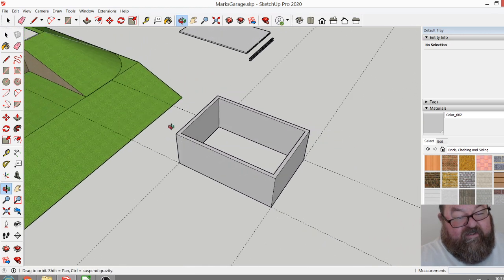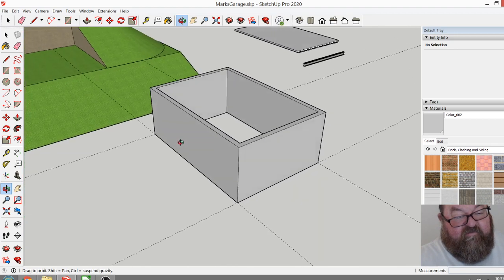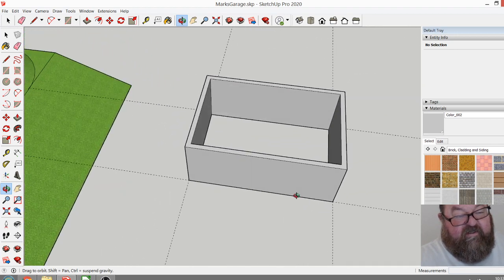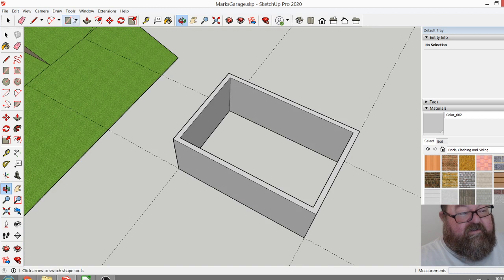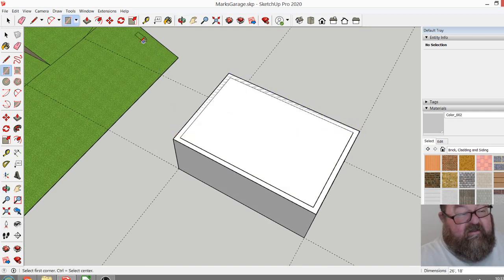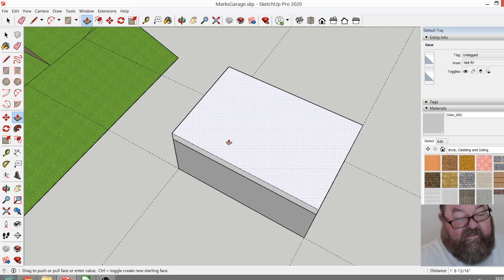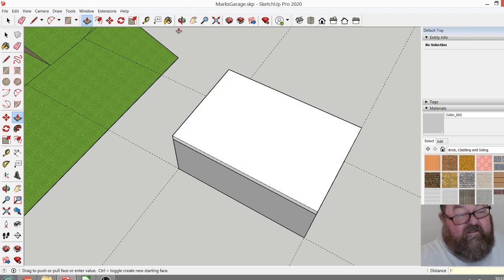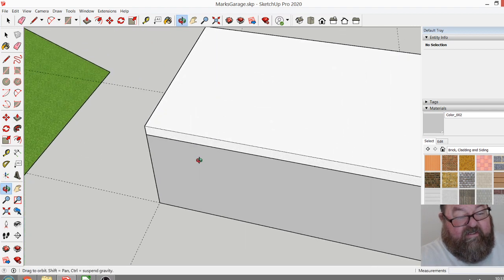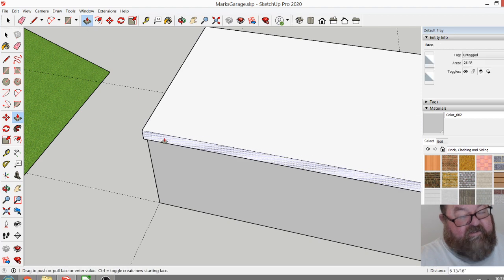Now we would have footings, obviously, and our footings for this would be at least probably, I'm just going to draw them up here in the air for now. I'll lower them in a minute. That would be at least a foot thick, so we'll come up 12 inches, and they would come out, I'm thinking at least, let's just say for now, let's see, I've got 10, let's just call it 16 inches.